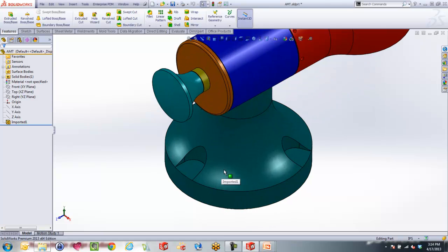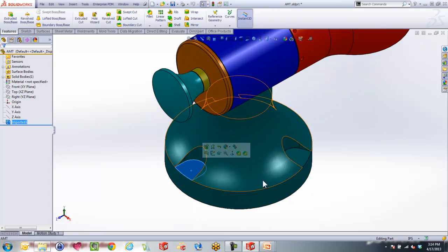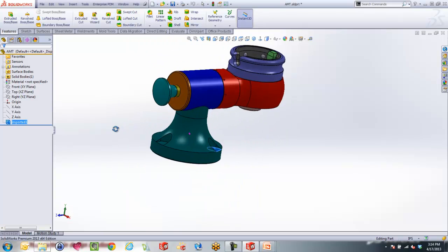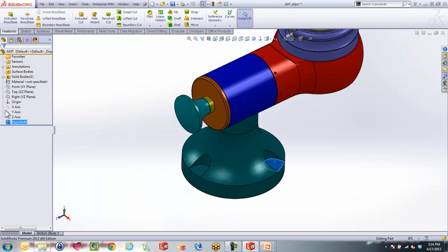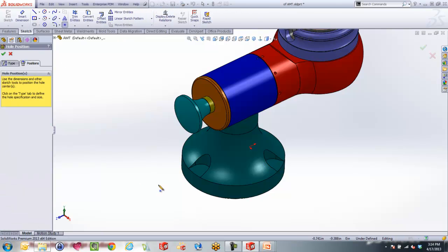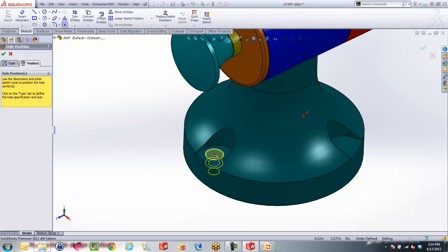In this part here, if all I know I need to do is add some counterbores, so this one can actually be mounted to a table, there's no need for me to do a lot other than just opening up my Hole Wizard and place my Hole Wizard holes on here, like this here.